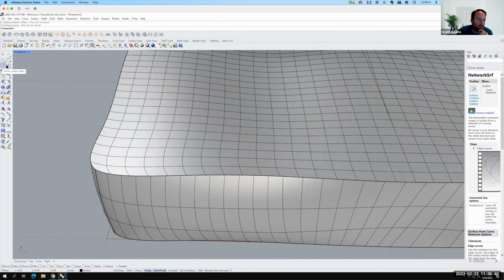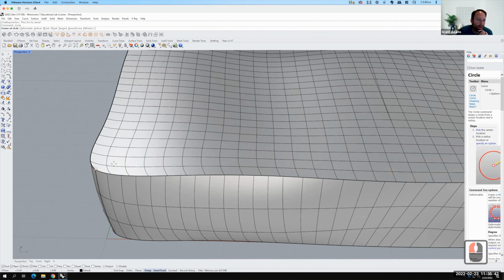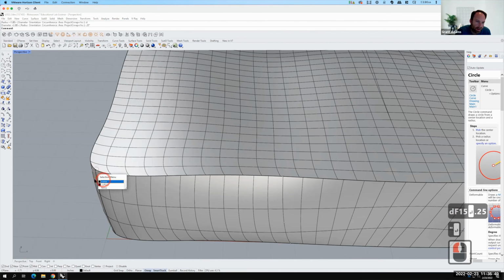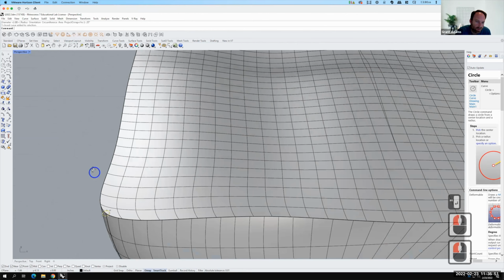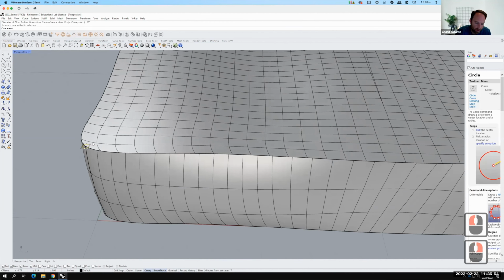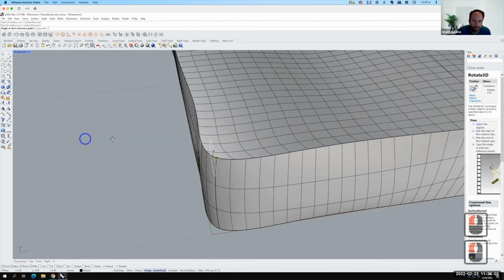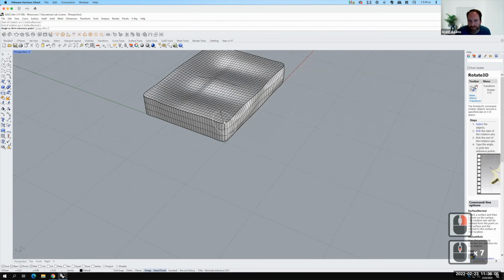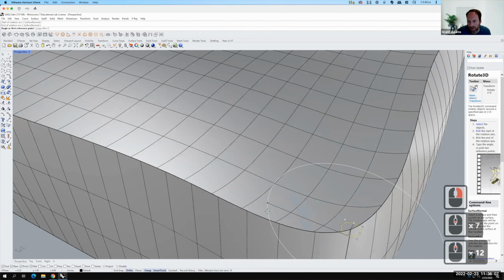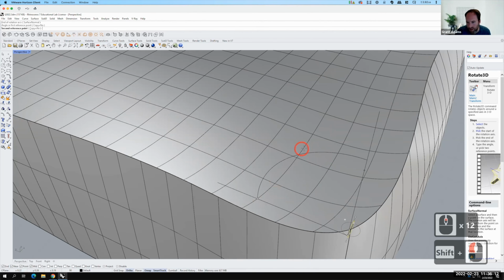So you might do a circle. Let's do the diameter of the circle at 1/4 of an inch. So now this circle is flat right now. It's laying flat. I need to rotate it up in 3 dimensions. So I'm going to do a rotate 3D. My angle is off, so it's hard to see. I'm going to hold down Shift so that I'm going off in space here. There it is. And we'll fold that one up.